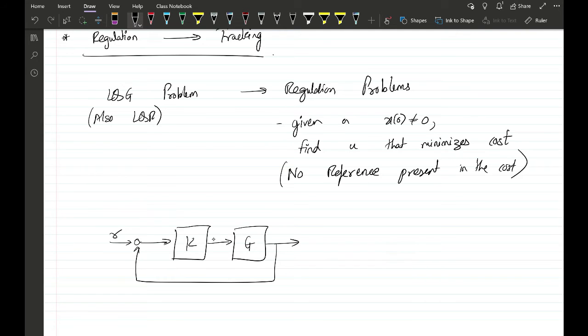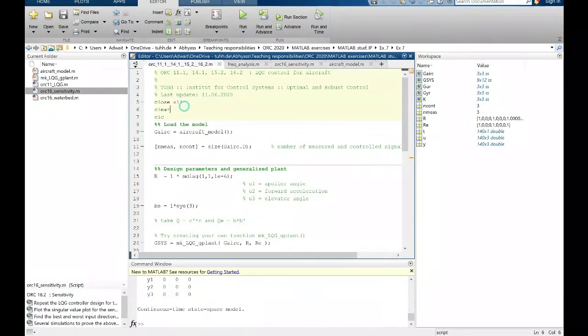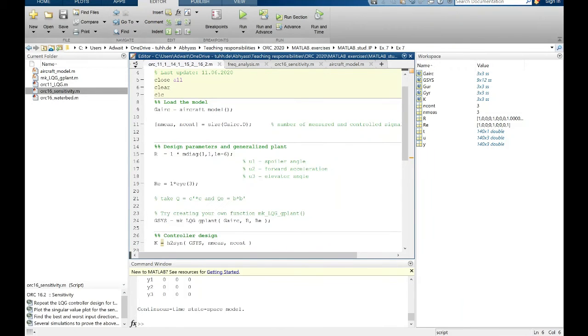So let's now have a look at the Matlab code quickly to see how this is all being done. Here you see again the file that you should have from the link and from std_ip. We first define the model matrices, we get the sizes of the control inputs and the output to the controller. So nmes and ncont are basically the sizes of y and u respectively.